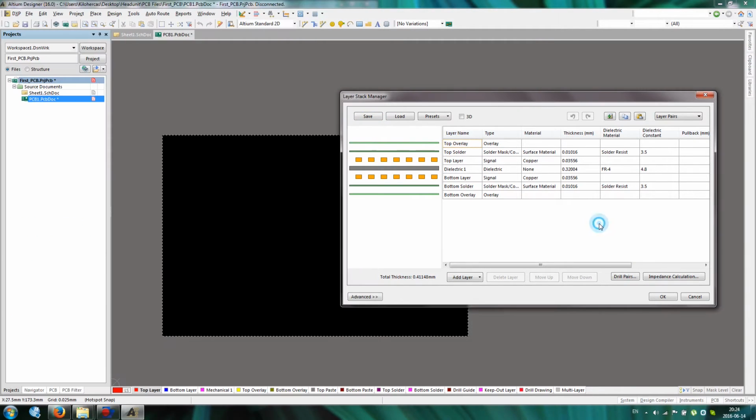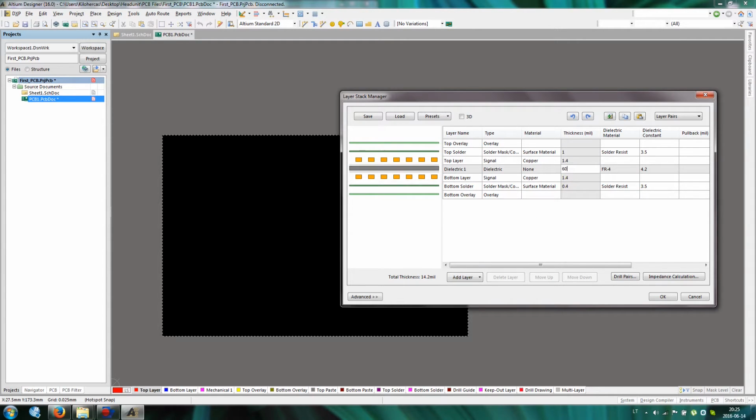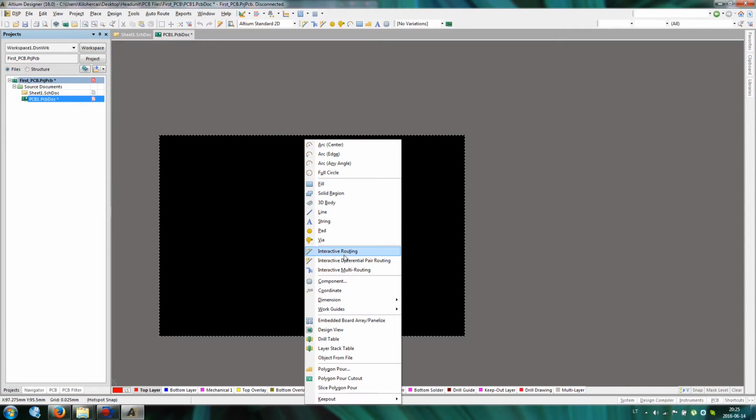60 mil copper. Okay, if you press Ctrl and Q, it will toggle between imperial and metric. Because it is metric, imperial, just use imperial, and it will be 1. If we want to use like 4 layers, we just add layer, and it will create a 4-layer board, but we don't need it. Okay, go to 60. Okay, so board thickness will be 0.6. That sounds okay.